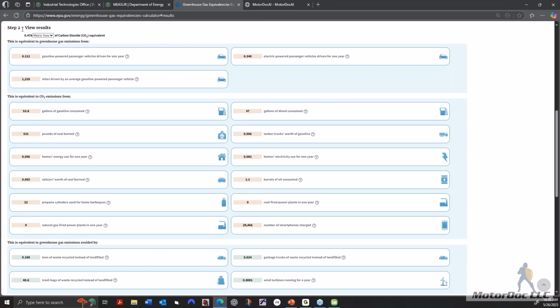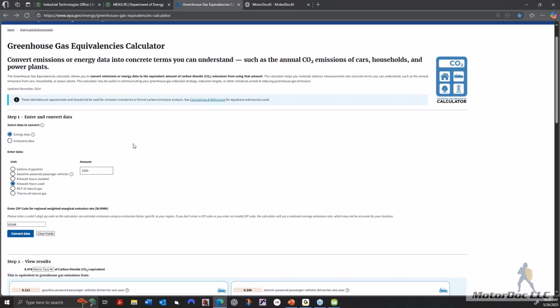So this allows me to go through and do an example. Let's say I do something and I measure before and after, and I reduce my losses in a machine because I replace the belts, and I take kilowatt hours before and after, and I reduce it by 8 kilowatts. So 8 times 8760 is 70,080.